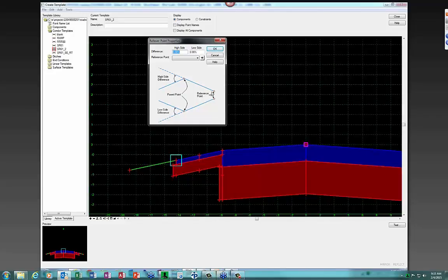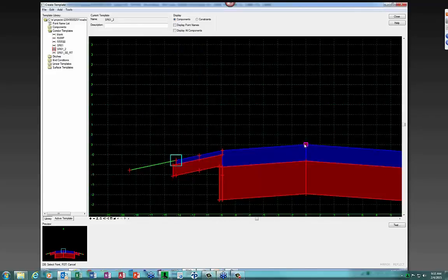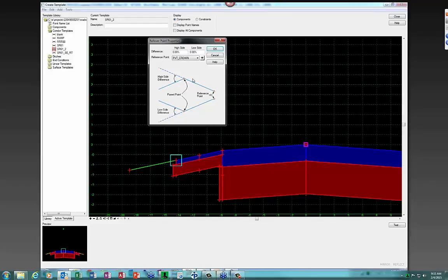And so what you're really trying to do is, this is the parent point that this came from. So that's this middle one. And then it wants to know in reference to, what's the next point out? So this would be the reference point. So all you've got to do is go into this one and skip over this one, because this is a vector offset. Know that this is the parent, and then just pick this point over here. And of course, this is recorded, so I don't expect you all to memorize this.